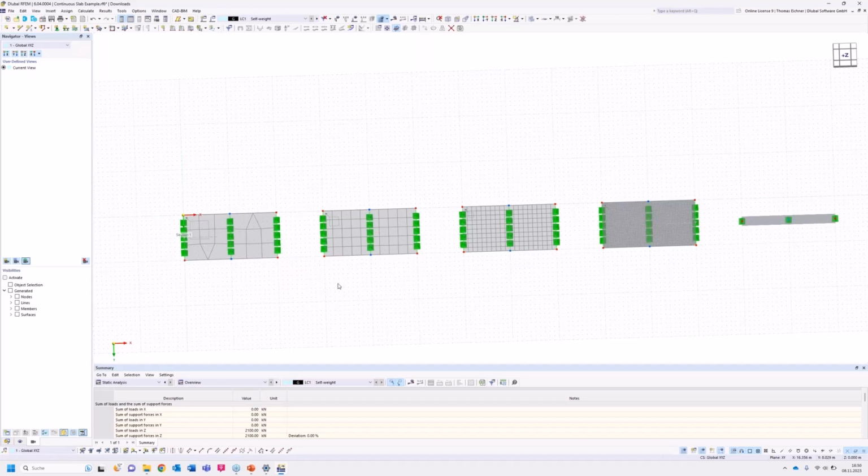That's for design. What I learned in this company is also that for bigger models there's sometimes the possibility that you want to design parts of the model and you want to use other parts of the model just for load transfer. And if parts of the model are just for load transfer, 4 elements are enough. Maybe even 3. But however, this one should be avoided in any case.